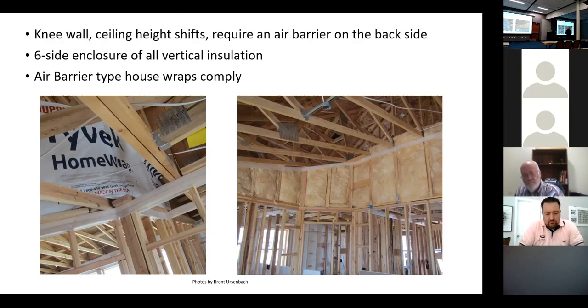The only time you're going to get a warranty on a roof is if you have a shingle failure, the material, the gravel or the mineral coming off in the first few years. If it's 8 or 10 years down and they start blowing off, they'll come out and say, well, it's not ventilated right, it's not this, it's not that. I've never heard of anybody getting a warranty on shingles 10 or 15 years down the road. But take it with a grain of salt.